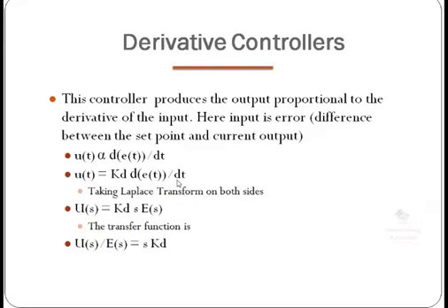Error is constantly 40. What is the rate of change? 0. So error is there as 40, but the control action is producing 0. What will happen? There will not be any control action, so the entire system will collapse. So derivative control cannot be used alone.